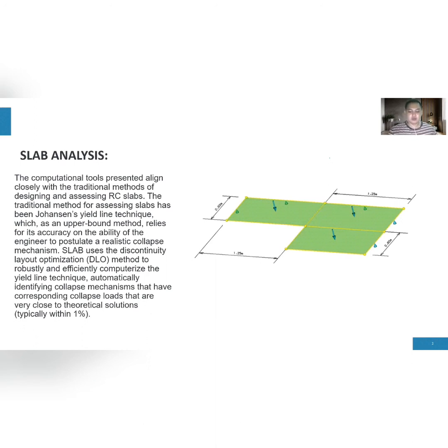So DLO is an engineering analysis procedure that can be used to directly establish the amount of load that can be carried by a solid structure prior to collapse. Using DLO, the layout of failure planes in a collapsing structure are identified using mathematical optimization methods. It is assumed that failure occurs in a ductile or plastic manner.